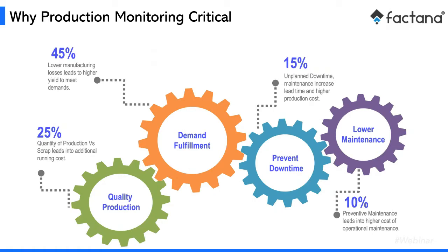The maintenance or downtime, right? The downtime of the machines, to prevent the downtime. We cannot have breaks and casual loading and resetting things happen, which we did before the pandemic. Now if you are looking at improving the efficiency, we need to put more focus towards the availability of the machines, and how efficiently we are using the machines, how efficiently we are aligning our process to feed the raw materials to the machine so that the machine can produce, as well as properly track the availability, especially usage and utilization, to understand the criticality of the machine, and when and where we have to do the preventive maintenance works, right? That is very important.